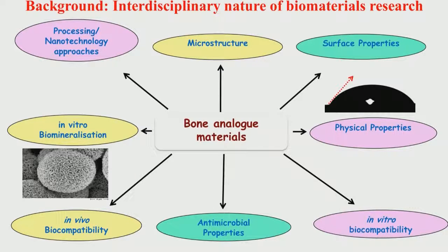They are more or less perfectly spherical in shape. More importantly, one can notice that these nodules have a very fine pore structure, a microporous structure. This porosity is much less than 1 micron. This kind of hydroxyapatite based nodule formation reflects the ability of that specific material to induce biomineralization. Biomineralization essentially means the ability of a material to form a surface mineralized layer, a surface layer enriched with calcium phosphate like composition, in simulated body fluid or in biologically or physiologically relevant media.